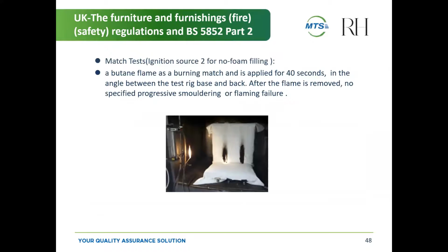Now here's the match ignition source 2. This is for no foam filling. Here they're using the butane flame as opposed to an actual burning match, and it's applied for 40 seconds. They want to make sure there's no progressive smoldering or flaming failure, so they'll watch this closely as well.